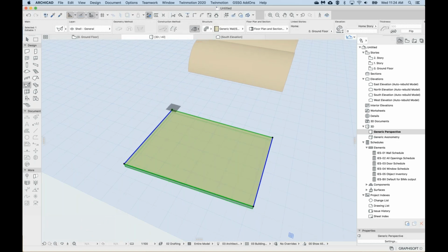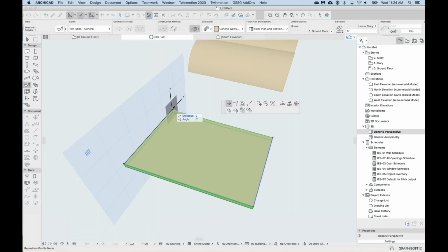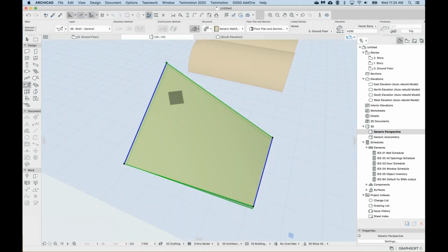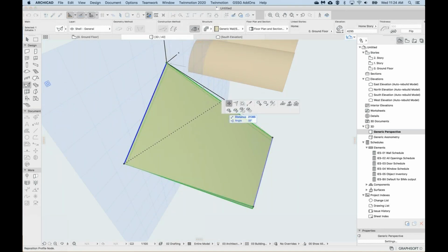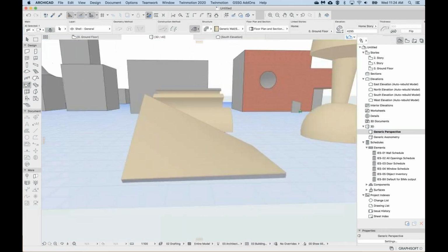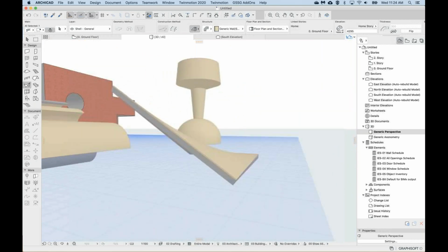Okay, so the one corner, we're going to click on one of these corners, and we're going to use the move node, and we're going to move that node up. So try to snap to the Y, and in my case, it's the Y axis. So I'm just bringing 1 point up. So I just clicked on the node and used the move node, so the first option on the top row, and just move that vertically up. So we have 1 point that's up.